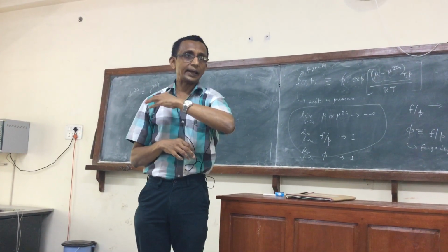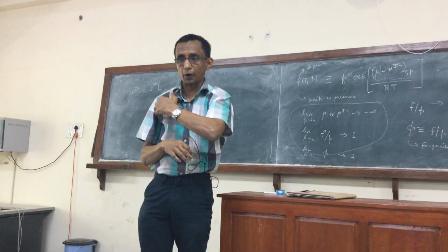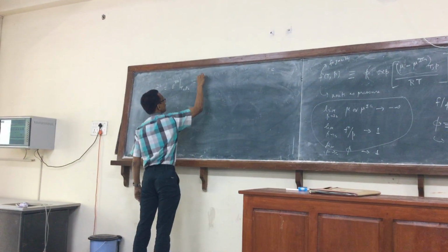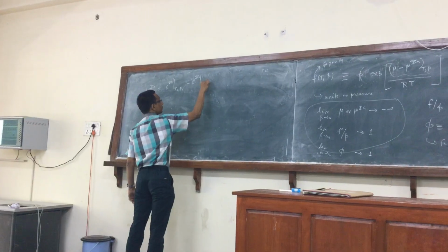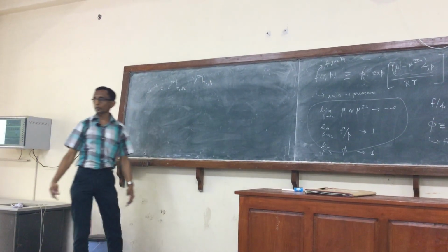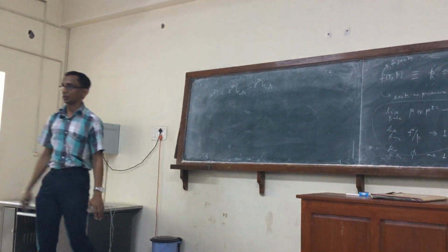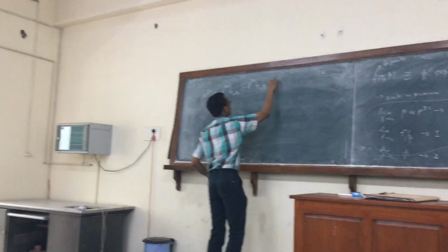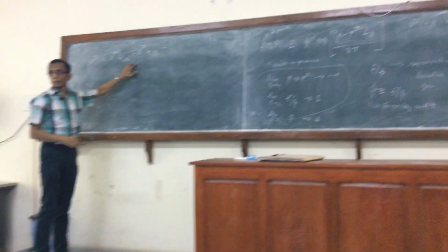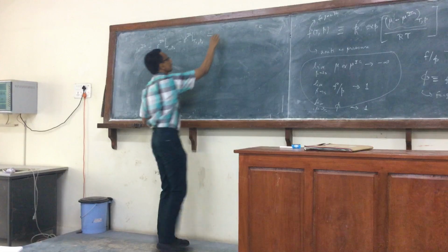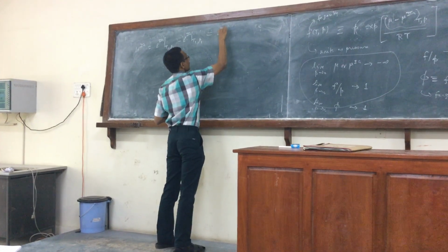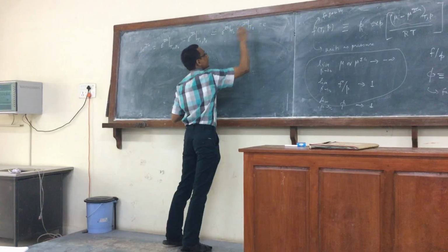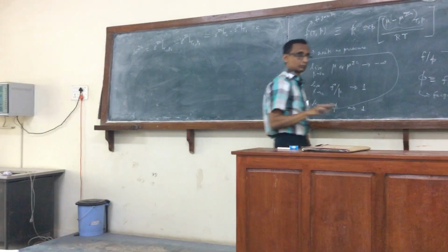So for that state, I want the ideal gas property, minus this. If T and P are specified, this is what the delta EIG would mean. Now, we know that the internal energy of the ideal gas is independent of the pressure, so I can write this as a function of T2 only. It's only the temperature that will determine.